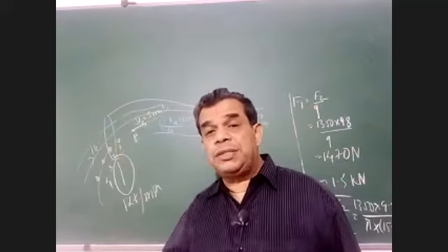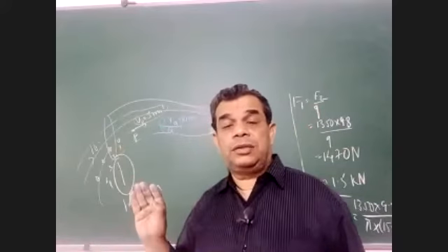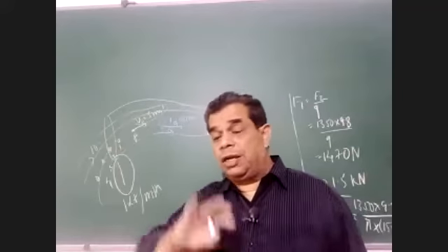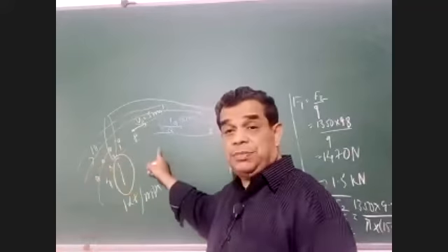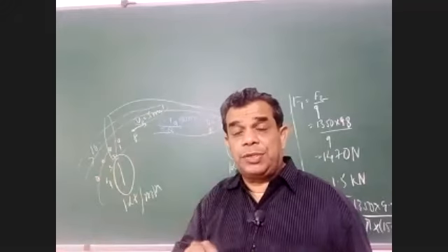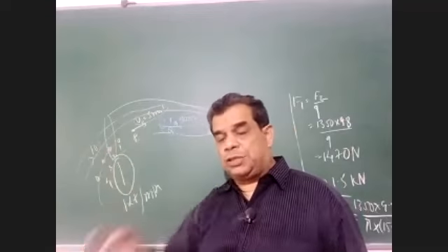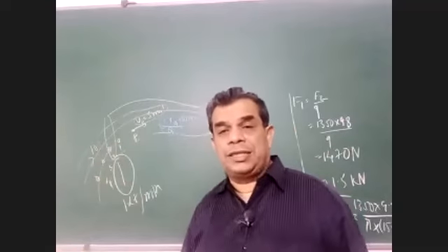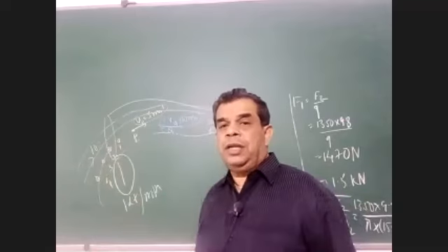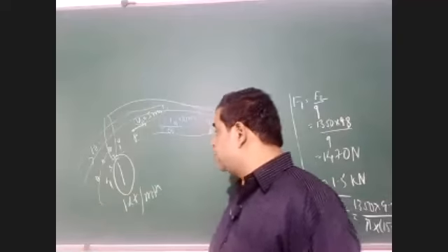Ideal fluid means there's no friction between the particles of the fluid. That we eliminated. And it is incompressible also, we are taking. In all these situations only this is possible: streamline flow. But it should be incompressible. It should be an ideal fluid, meaning there is no viscous force, no frictional force between the layers of the fluid. That's not possible in reality; that we think of later on. We go on introducing complications a little later. But before that, observe carefully.